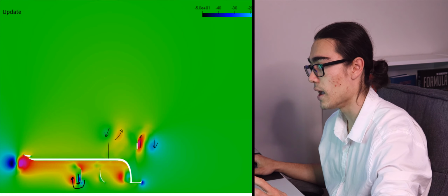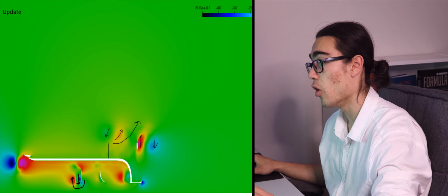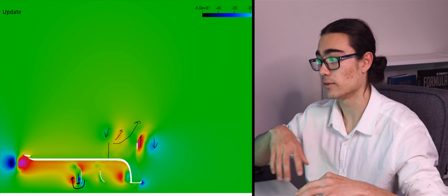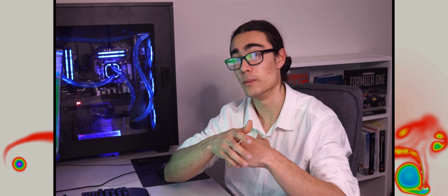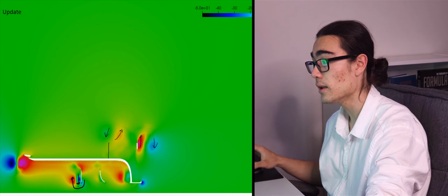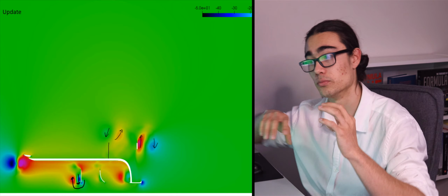So in this area here, we're now chucking air all the way up and outboard, and this is what's giving us our outwash and a little bit of upwash as well, to push air around the tyre so we can shove some of that wake a bit further outboard and we'll be better off for it downstream. So that's a really neat way to see where we're actually putting these vortices and how much interaction we're getting between them.